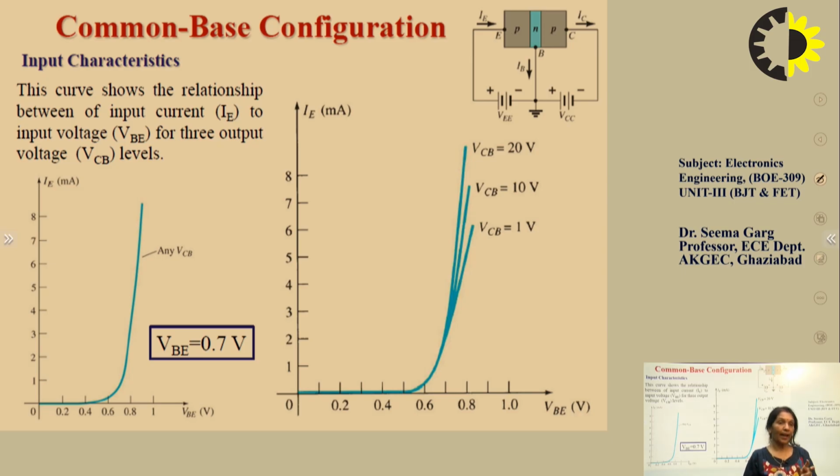So it is used as an impedance matching device in multi-stage voltage amplifiers, because it does the impedance matching between the 2 stages of the amplifier without disturbing the actual gain of the amplifier. So basically, the application of the common collector amplifier, or the emitter follower, is as an impedance matching device in multi-stage amplifiers to reduce the loading effect.